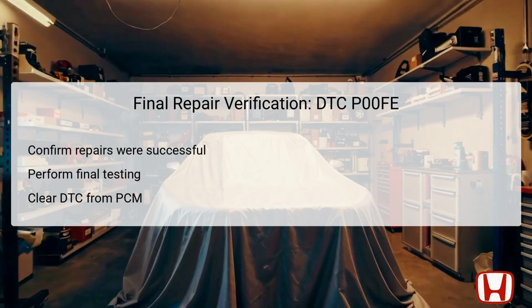Once the verification tests show successful operation, it is crucial to clear the diagnostic trouble code, DTC, from the powertrain control module, PCM. This ensures that any historical error is not lingering and causing unnecessary concern for the vehicle owner. A thorough final check helps maintain vehicle integrity and guarantees adherence to safety and emission standards.